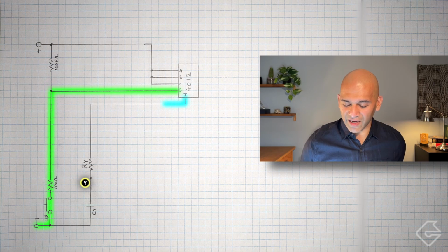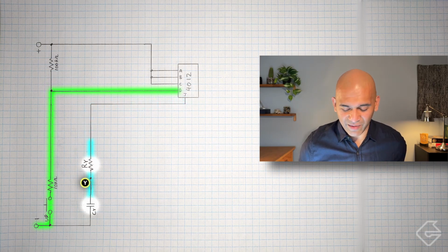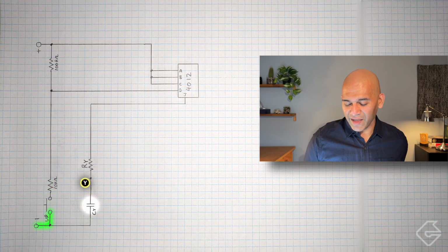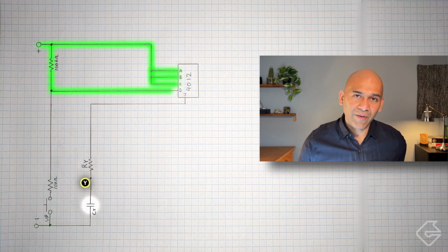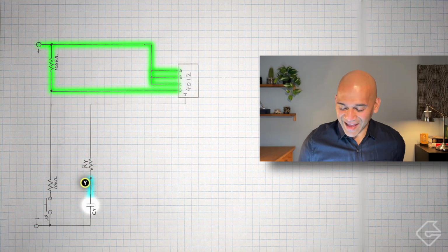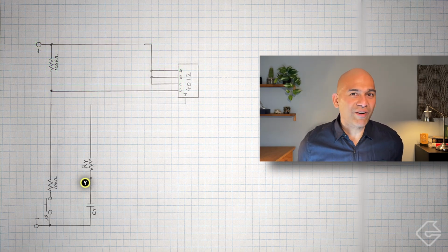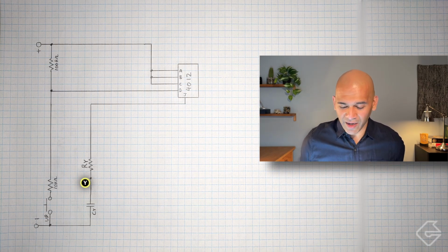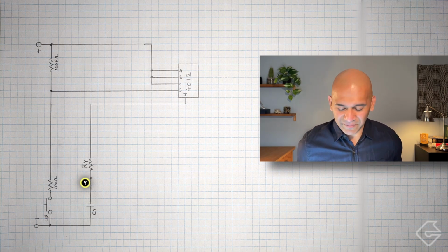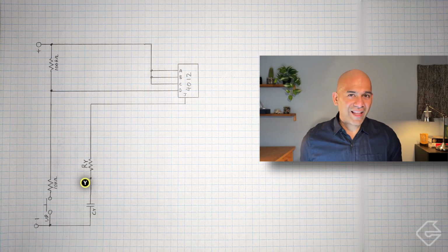So we're actually going to get a nice high over here whenever we push that button. When we release that button, this becomes a high. And since all the others are automatically tied to high, then the output over here is going to fall to 0, or fall to a low, and it's going to give us a low over here. And this path is also going to serve as that CMOS charging and discharging path. So that means that this capacitor will be charged through RY and discharged through RY. So I think that's going to allow us to control point Y as well.